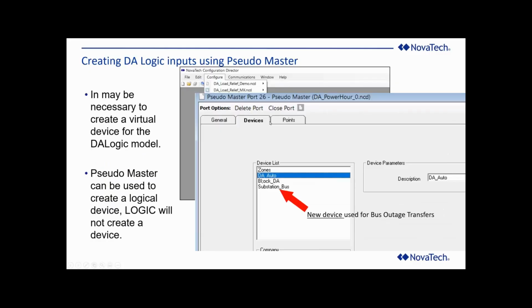One other thing that I mentioned earlier was in the safety interlocks. We have an auto manual safety interlock that has to be created as a virtual point. There's many ways that you can create that. You can create them in logic, and each one of those points would be a master auto manual at logic, if anybody is familiar with how the logic master protocol works.